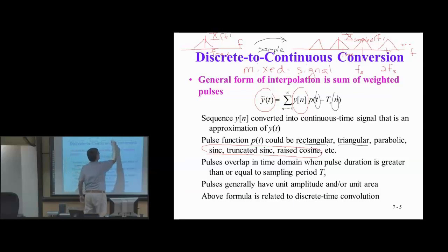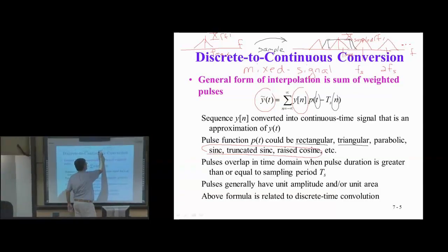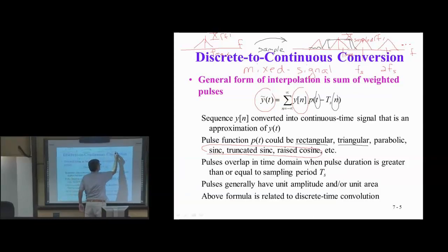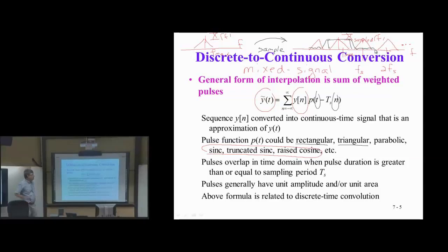We're going to put in an ideal low-pass filter. It's all ideal in this discussion so far. So I want a low-pass filter that extracts the baseband component and rejects the rest. Now, of course, in practice, we can't do this. In practice, you really have a filter that will roll off from passband to stopband, and the stopband won't be exactly 0. So we will always have some aliasing, or in this case some imaging, some frequencies that get through.